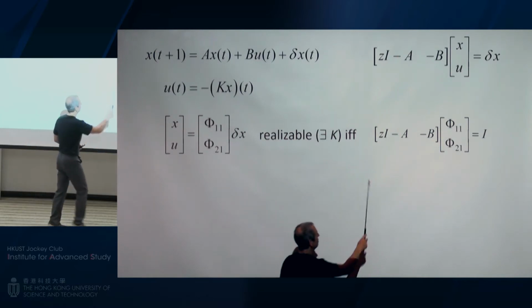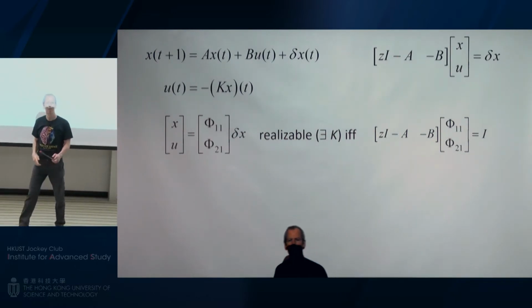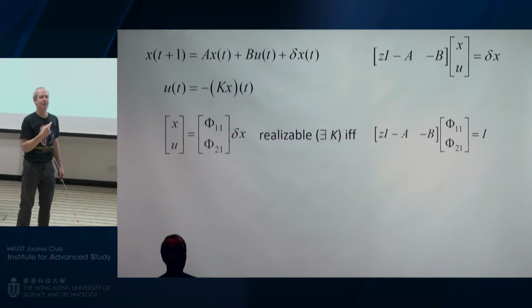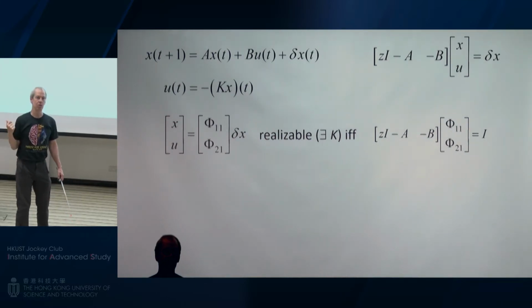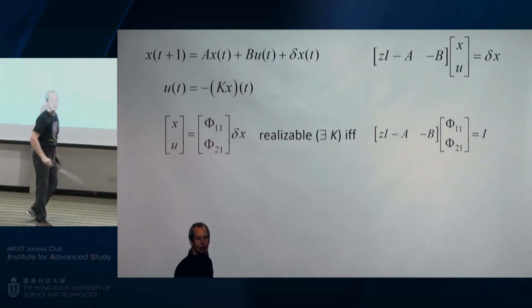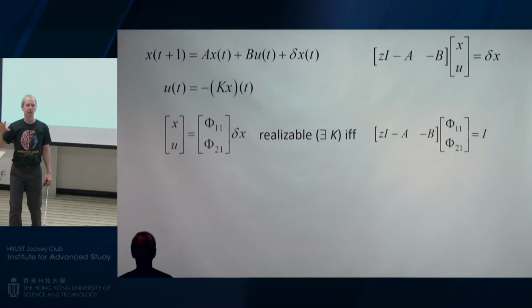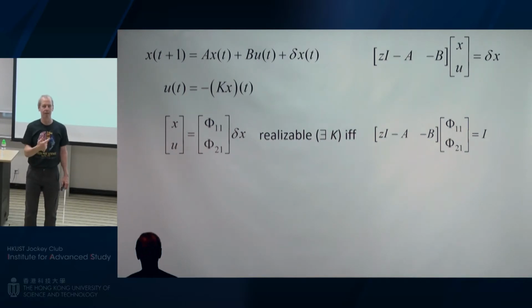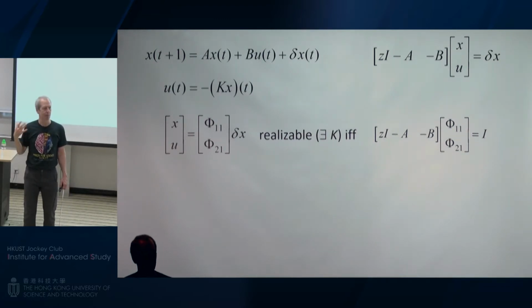Well, it's an algebraic condition. That's it. It's an affine condition. It basically looks like stabilizability. But the nice thing is, that's an affine condition. Everything else I want to do is convex in these variables. So I can now put convex constraints on sparsity, delay, everything I want. And then I just check this simple condition, whether or not I can get a controller that does that. Or I can just put all these constraints in and let Steve Boyd give me an optimal controller. Now I can't solve Riccati equations anymore, but it's convex optimization, no problem. And it's going to be localized, so it's really cheap and really small. Now I can design everything I ever wanted, just about.